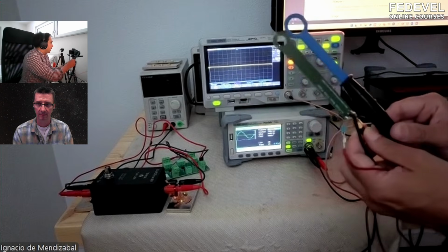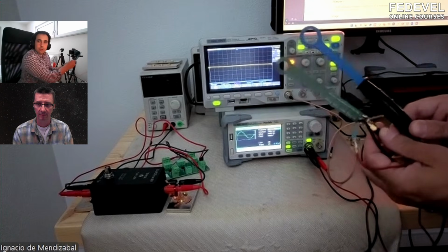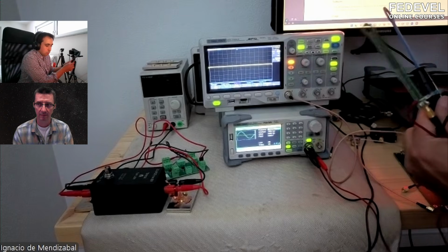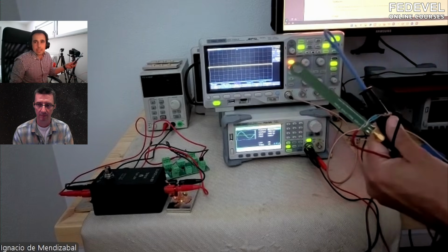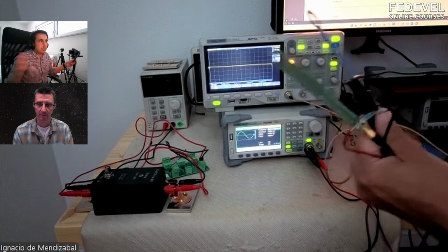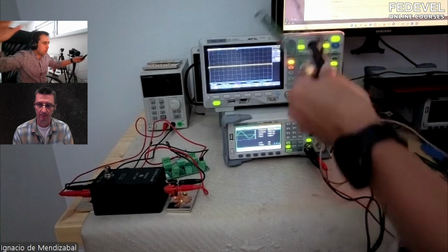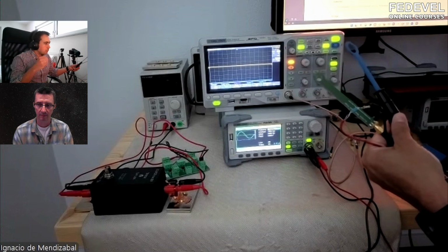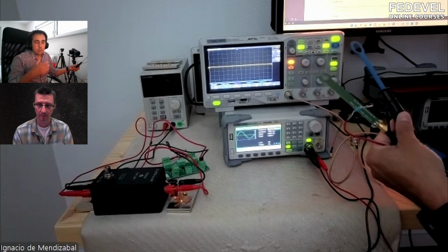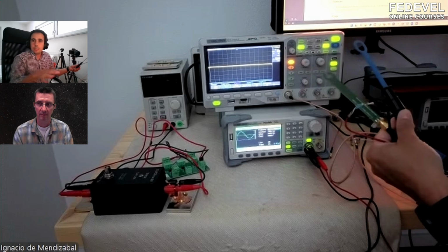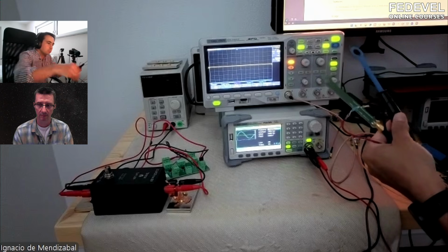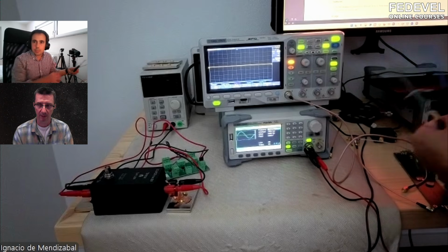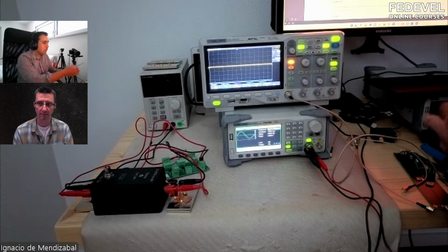Why is the circle different? Because of the sensitivity. The bigger the probe, the higher the sensitivity, and that means you can start capturing signals from broad areas. It's a good step for starting to answer whether there is some noise in this area or not. Then later you go for smaller probes that help you narrow down the specific component or specific area. Yeah, that's it.